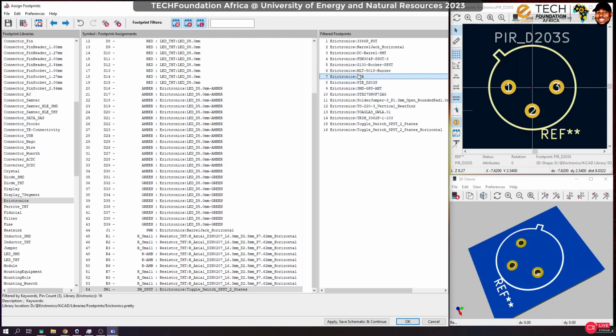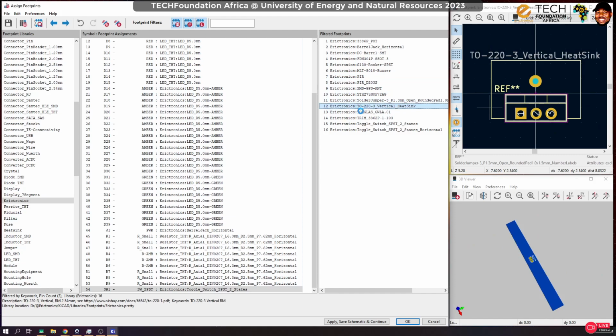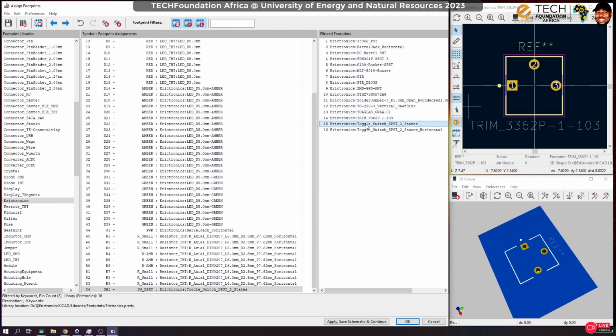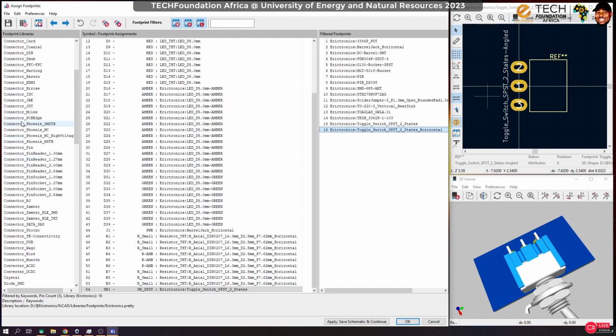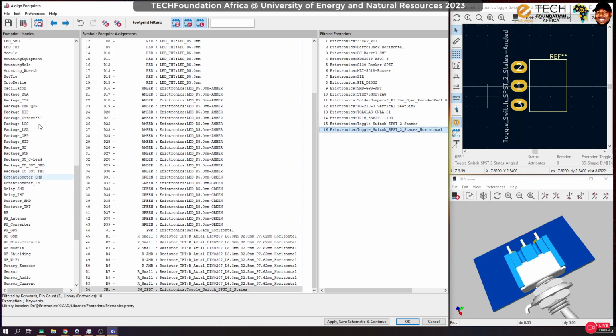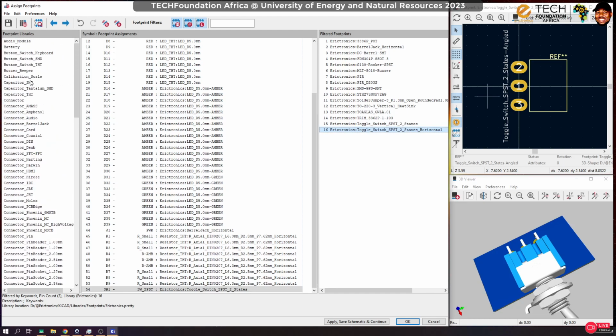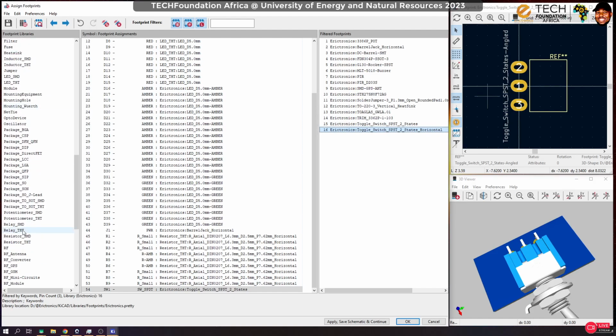Take note that if you select a wrong footprint, you would end up discarding your PCB, okay? Because then the components are not going to fit. All right, so let's go to KiCad libraries and see if we can get a switch for ourselves. So we need a switch. We need a switch. Where are you? Hmm. We need a switch.